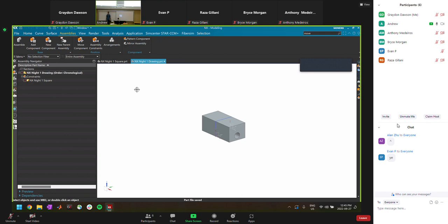And in SolidWorks, there's all the different configuration stuff that you can do, and you can have different views hidden, this and that. And so essentially we've just made an assembly, and that assembly is going to be our drawing file, so that we can add multiple different versions of this part.